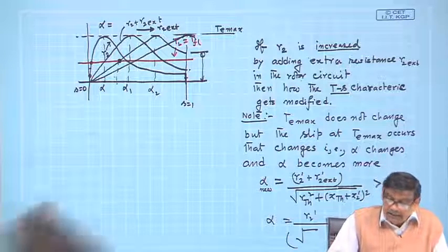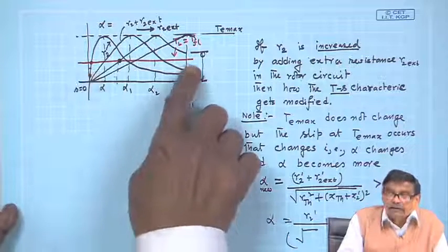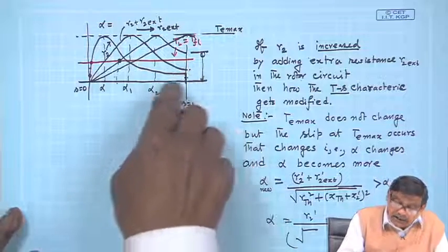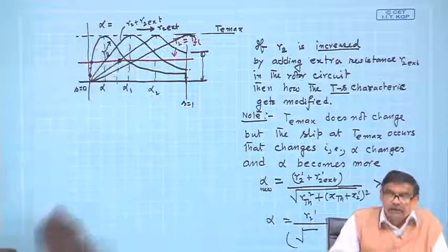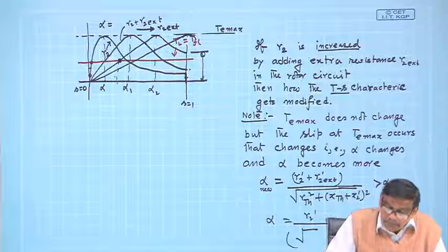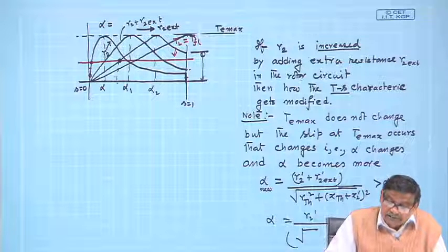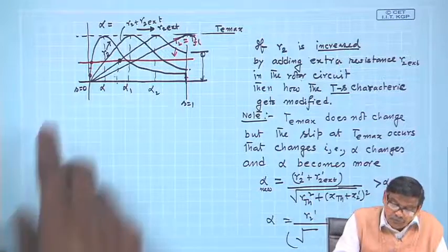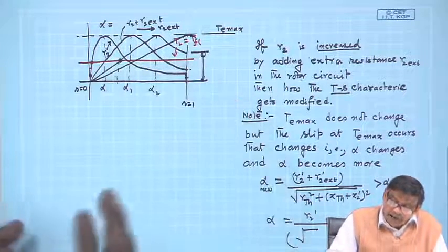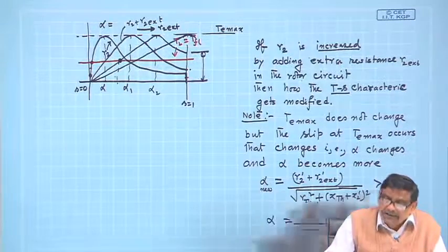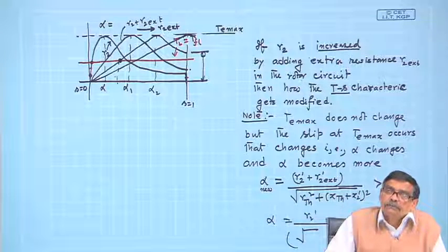Therefore, not only that, this problem that with inherent rotor resistance, although the machine is capable of starting, against full load torque, one way out is do not connect that full load opposing torque at the beginning.